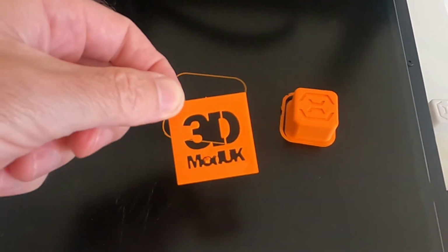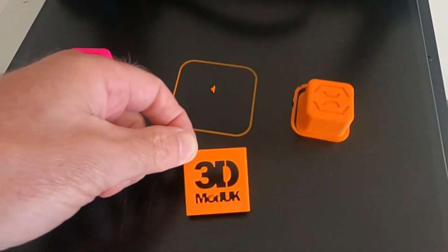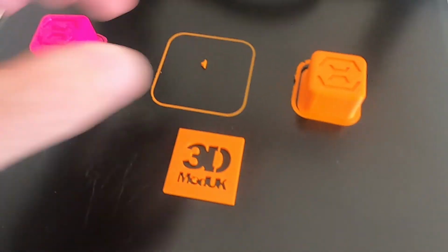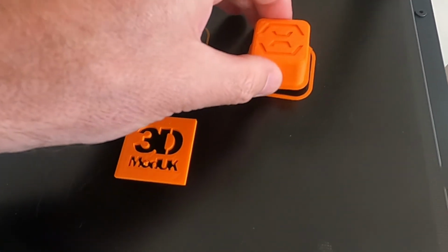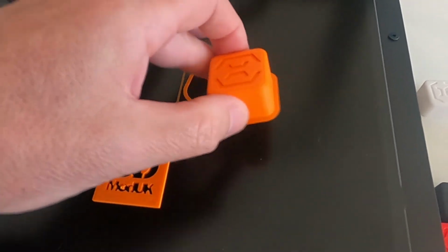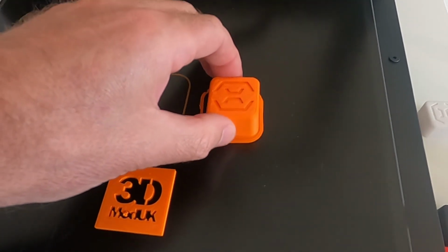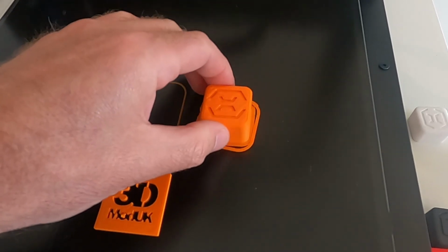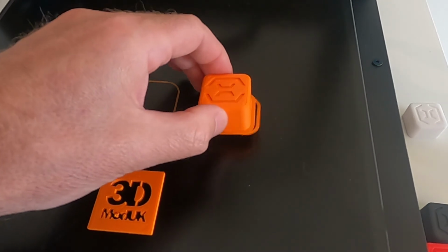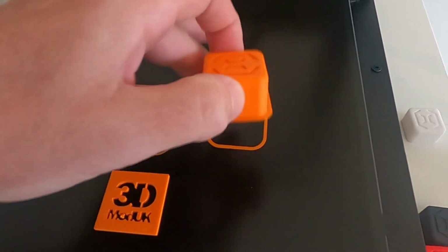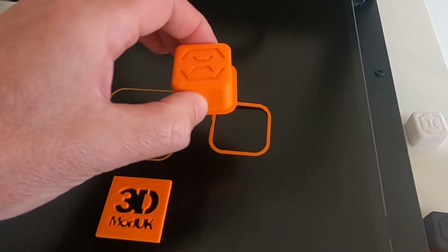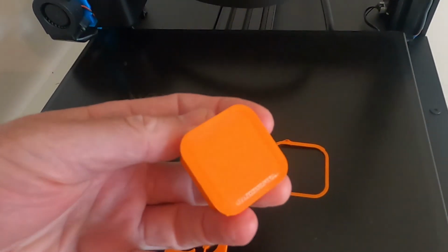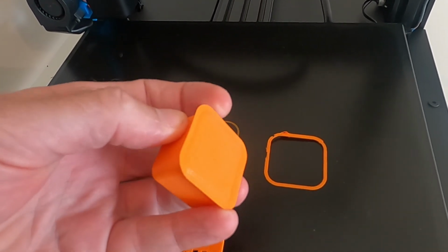But one of the things I found with this particular orange filament by ICE Filaments is that I think it might have been a little bit too hot, the temperature, because one of the issues I had with the test cube, and this is one of the reasons why I like to do these different tests, to see how a consistent print differs with different filament, is that when I removed that from the bed, whilst you got this outer brim, I think it's called, you've actually got some of the brim left against the actual cube itself, so it hasn't come away, it's part of it.